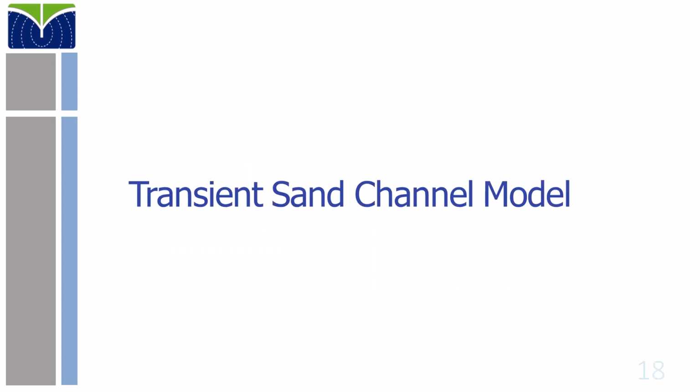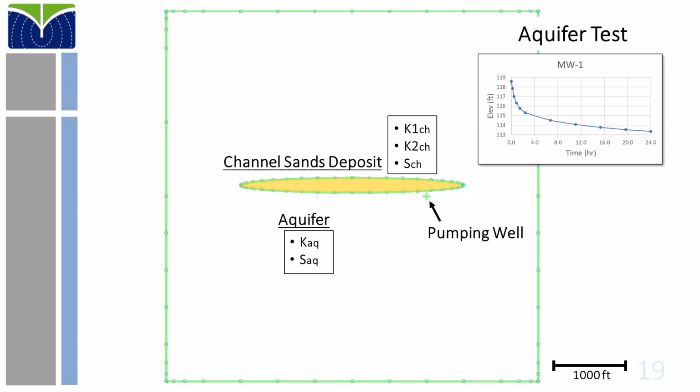But suppose you were asked to plan an aquifer test and to determine the best observation well locations. That is what we are going to examine in the next example. Suppose that you have developed a very simple AEM box model for your site. Your site consists of an aquifer area about 1 mile by 1 mile with a buried channel sands deposit running from west to east near the central area of interest at your site.